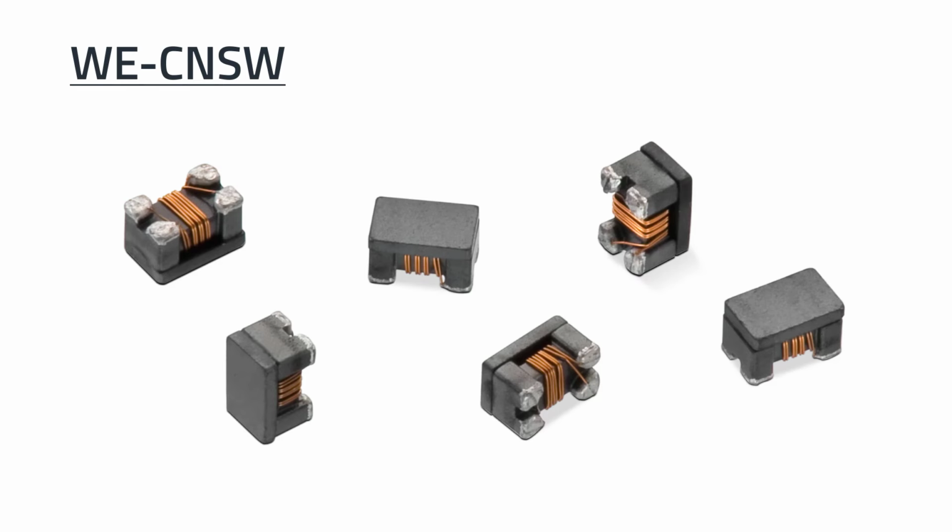Make sure to pay close attention to the frequency response, current handling capability, and other relevant parameters of the choke. For this application example, a suitable choke with a differential mode impedance less than the max and a high common mode impedance is 744233900. This is our WE-CNSW high-frequency surface mount common mode line filter.